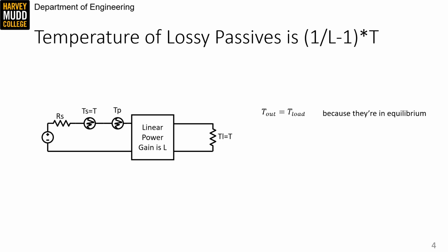To do so, we can observe that we're assuming we're in thermal equilibrium, which means that the noise emitted by the two-port has to be equal to the noise emitted by the load. If that wasn't true, one resistor would be providing power to the other. We can calculate the noise power at the output by multiplying the input powers by the power gain. As a reminder, the power gain is like the transfer function squared, so this is consistent with our previous finding that we refer noise to different places in a circuit using the transfer function squared. Also, noise temperatures are linearly related to variance densities, so it's fine for us to add them. We're using the symbol L for power gain here to indicate that this system is actually going to have a loss, which means L is expected to be less than 1.